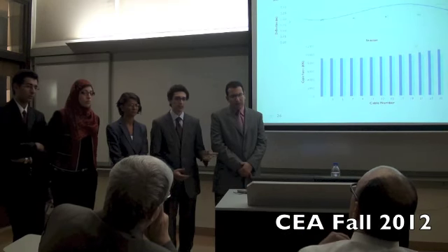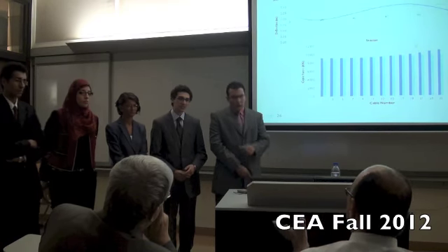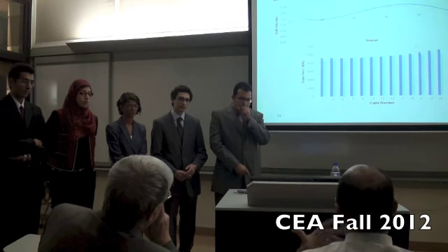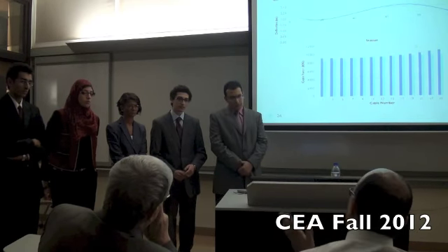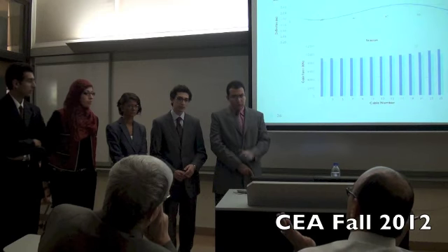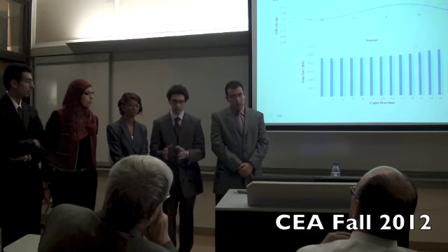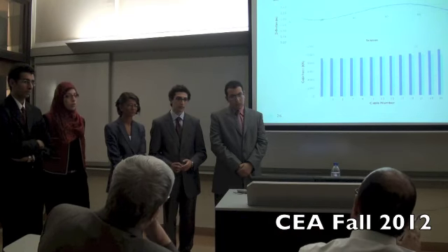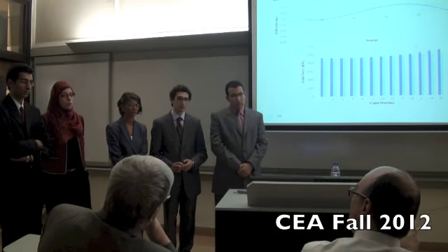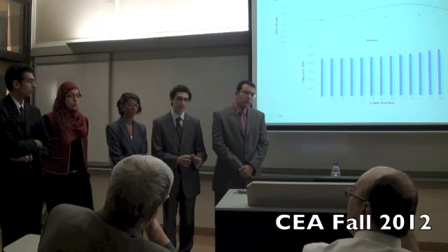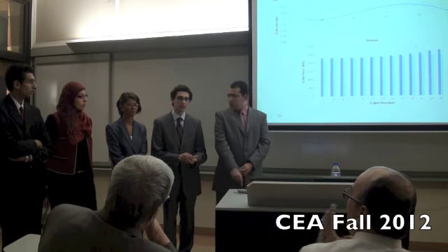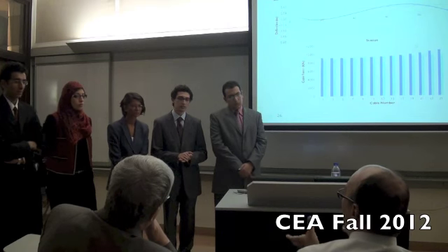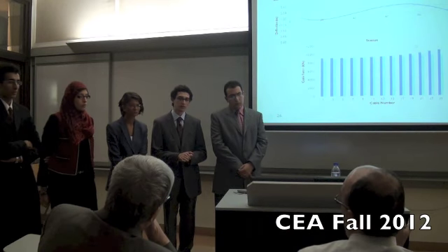But for the area elements, your computational requirement is the maximum with the non-linear and full loading, half an hour with grillage. That's why we substitute, and do not use a full model. 3D analysis uses area or solid elements. So if you are telling me that your model is taking half an hour, your full model may take 1 day.